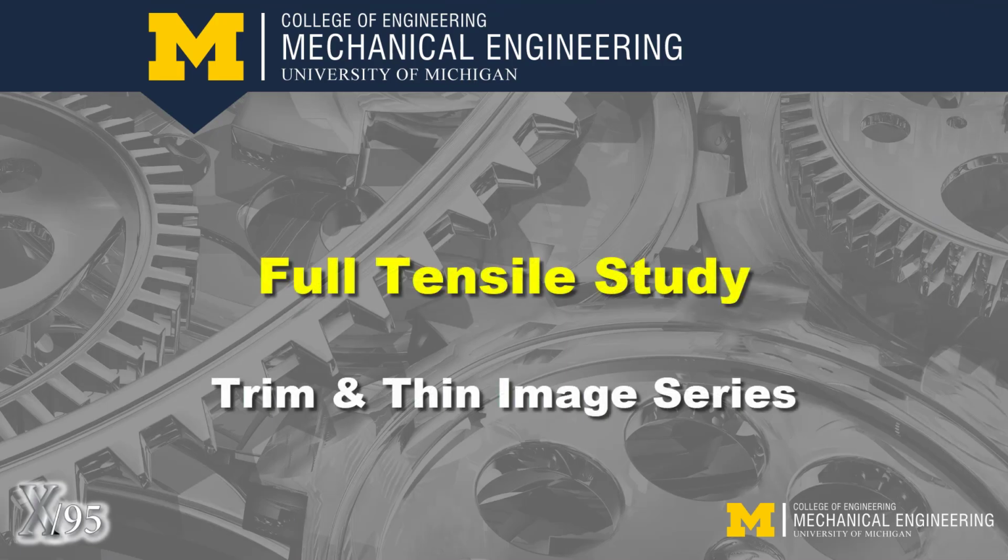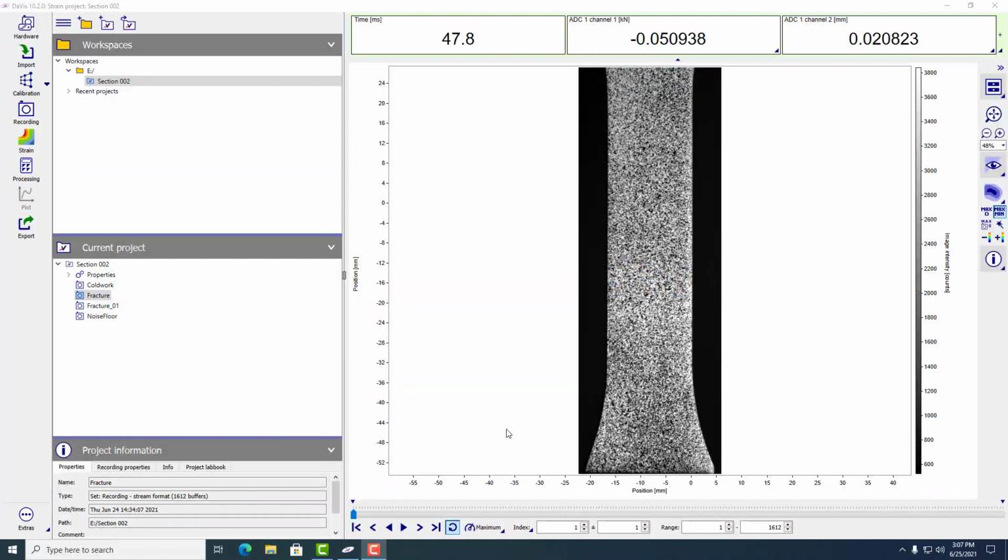The image range needs to be trimmed to eliminate any initial dead time and post-fracture period, which is all garbage data. Drag the cursor along the timeline and monitor the load to determine the onset of loading. Use the up-down arrows to slowly increment by frame. In this case, the load jumps around frame 14. We'll set frame 10 as the start frame.